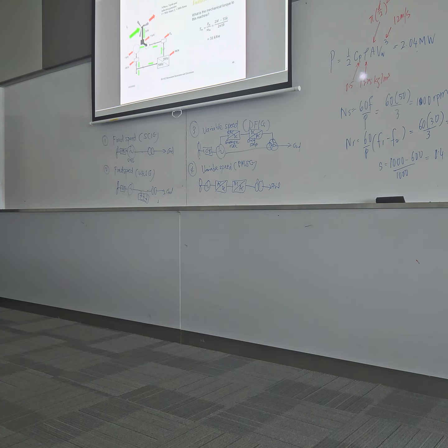Okay, you also can calculate values such as the torque. So your power P equals T omega. So when we want to calculate the torque, T equals P over omega M. The mechanical power is actually 2 megawatt, but because there's the 55 kilowatt loss here due to the gearbox, you have to deduct that.